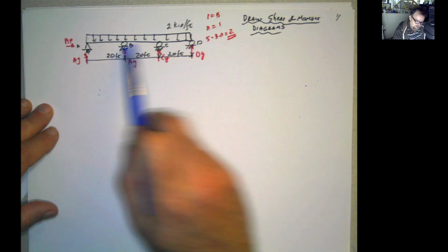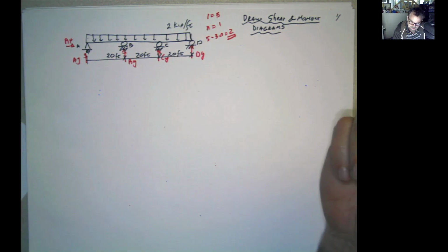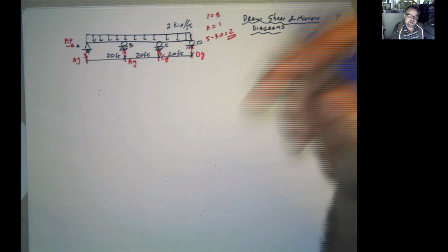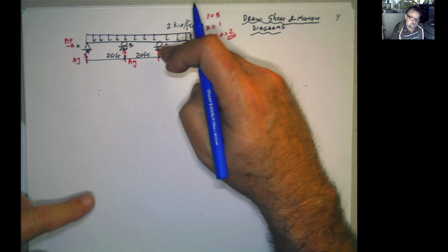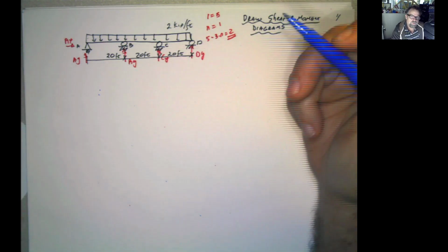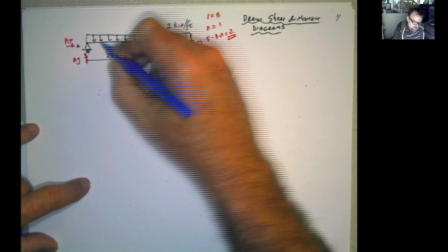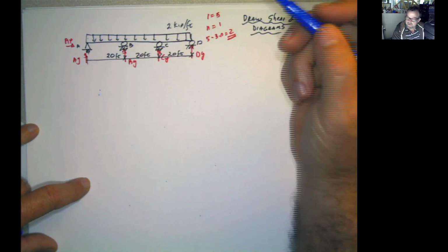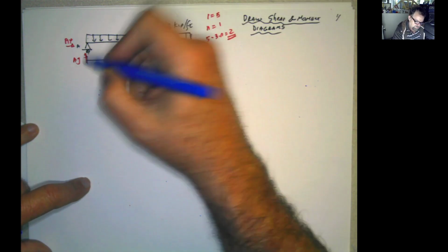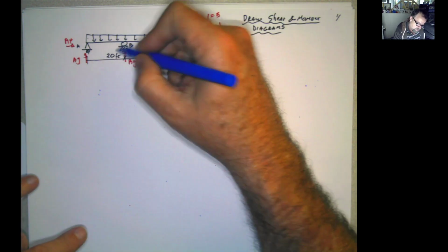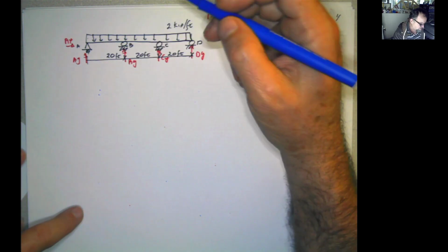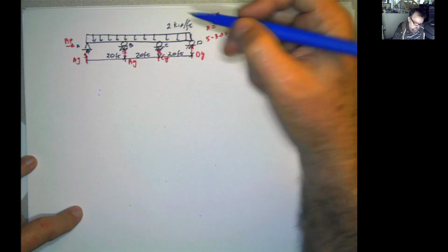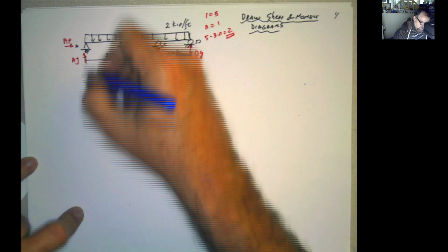Easier, B and C. You can eliminate anything. You can even eliminate one deflection and one rotation. You can do a bunch of things. You can put a hinge here and separate this into two parts. In that case, you eliminate the internal moment at that point, and then you apply a moment. It doesn't matter. Eliminate two redundants, but in this case the easiest way is to eliminate these two.